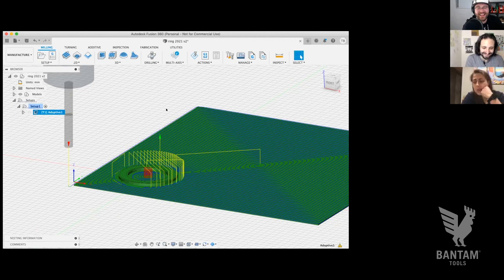Sorry, Pete, go ahead. I was just going to point out a couple things here immediately. If you're a more intermediate or advanced machinist, you'll see this immediately. But for somebody who's completely new, this is something that I did not recognize when I first started. Right now we still have a layer of stock even on this adaptive clearing pass, which means we're going to have to adjust our heights in that height tab that Pete was just mentioning. But that's a whole other thing.